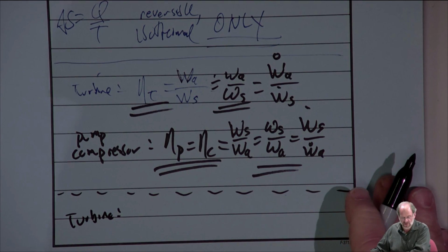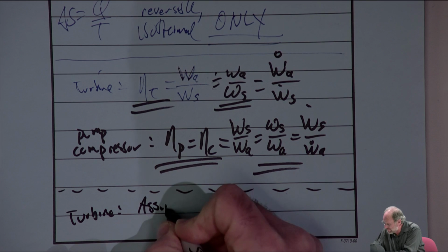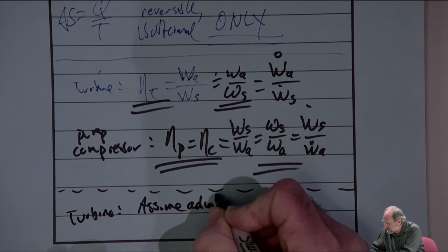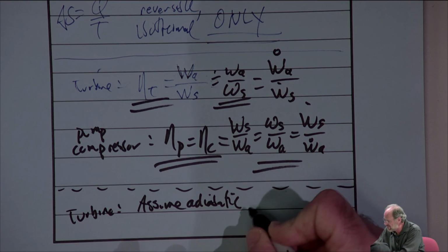And let's just first of all note that for these types of problems, we're always going to assume that it's adiabatic. In other words, no heat transfer, which makes sense, right? In the real world, your mechanical devices are going to be well insulated. You don't want to lose heat to the surroundings, so you insulate them, and that really minimizes the heat loss to the surroundings to the point where we can neglect it. So we're going to assume that it's adiabatic.